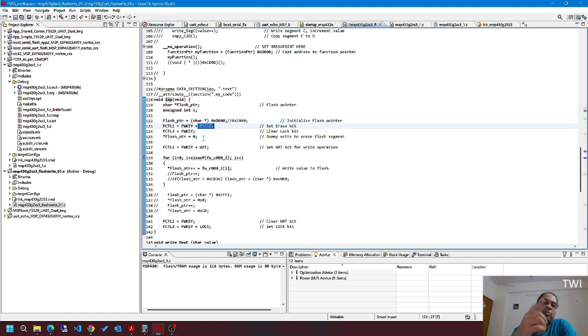One thing you must remember about flash memory is that flash memory controllers need it to be fully erased first, that is, erased with all ones. Flash memory is divided into multiple pages or segments, and each page or segment has to be first erased, where all its bits become 1, and then you can program your code so that you can have the zeros coming in. Which means that you can turn a bit from 1 to 0, but you cannot turn a bit from 0 to 1 without mass erase. So this mass erase, or the erase of that sector, is required first.